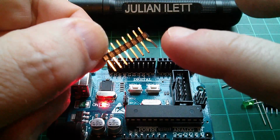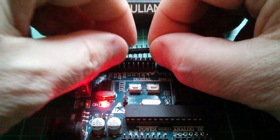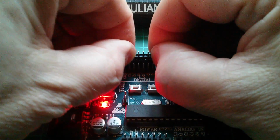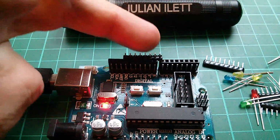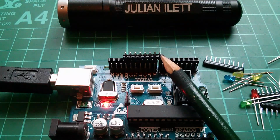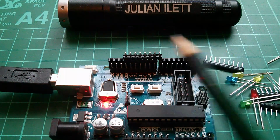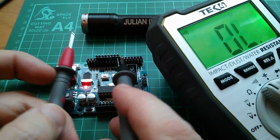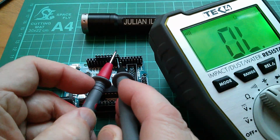I've had to bend that last pin out, but I think it's going to work now. That will go from ground on the left and span out over into the other connector block. I hope the pin's still long enough to get into pin 7. So I need LEDs on 7, 8, 9, and then the common pin of my resistor will go up to ground. Just going to do a quick continuity check to make sure that that is sitting in pin 7.